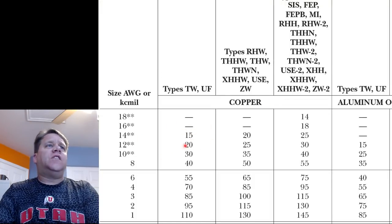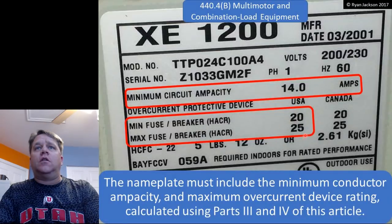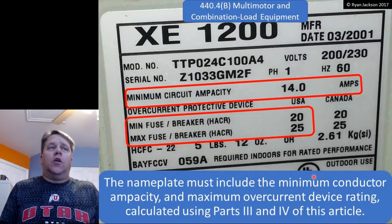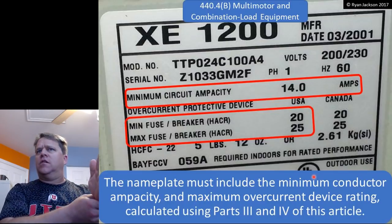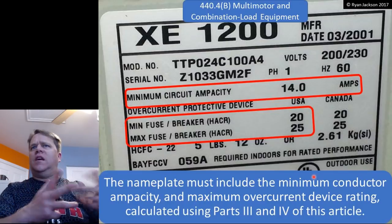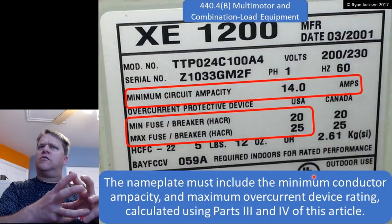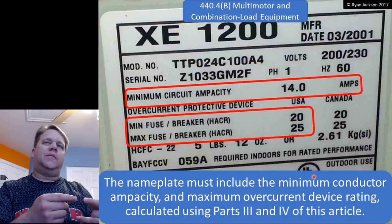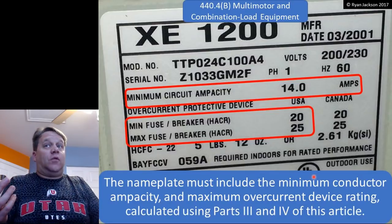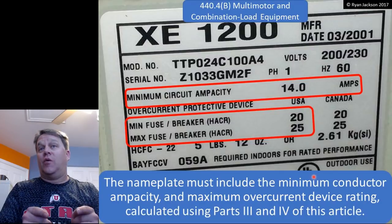If I put a 15 amp rated wire on a 25 amp breaker, how is that protected against overload? What happens if the shaft on the motor gets bent? A tree comes and hits the air conditioner and it jacks it up, right? So now all of a sudden the motor is struggling and it starts pulling 18 or 19 amps. Well, that 14 gauge wire is going to melt, right? Actually, it's not. Do you want to know why?